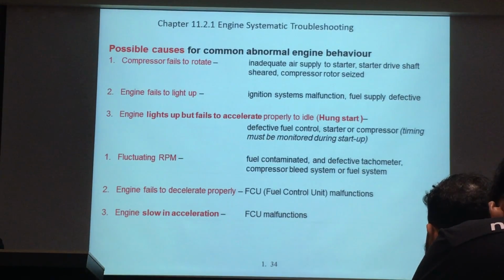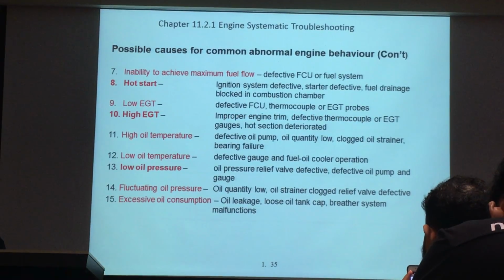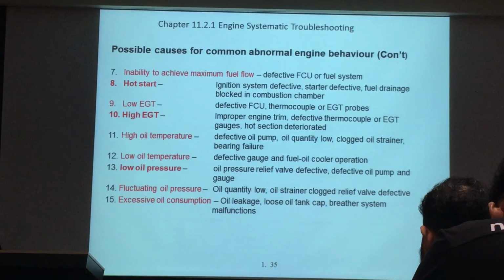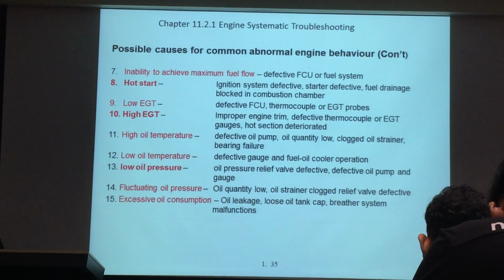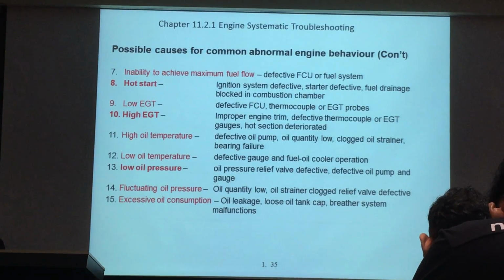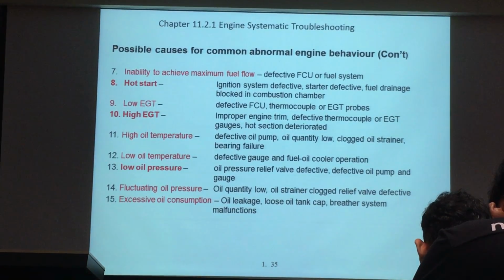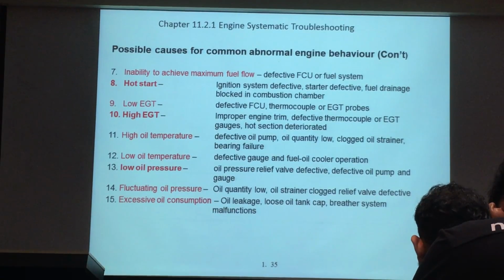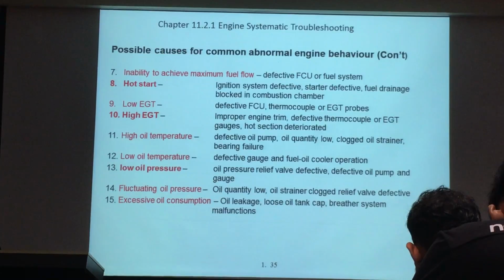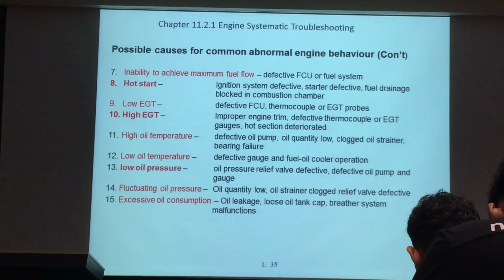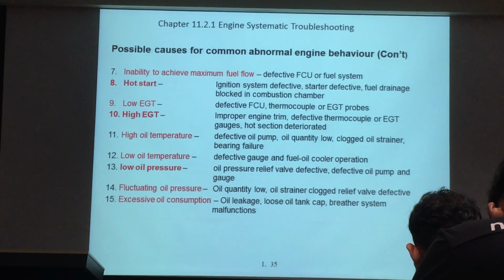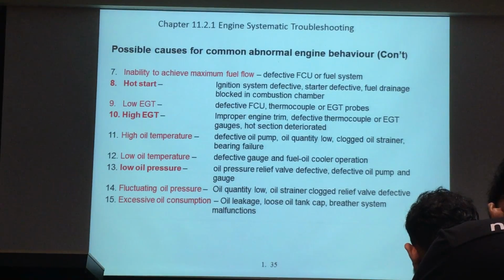Let's think of a few more failures. What is a hot start? The temperature rises too fast and hits your peak, so you must shut down the engine immediately. What is the cause? FCU failure. Very good, that is the common term. FCU failure can cause a lot of things: no light up, hot start, hung start.